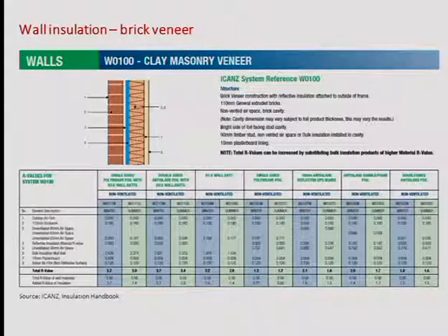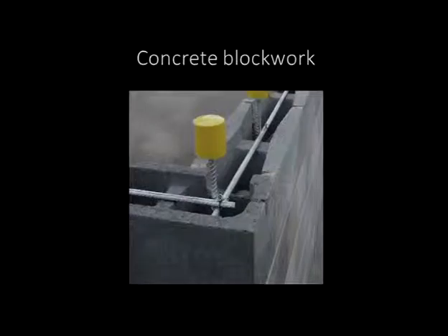All right? So even if there is the same material and type of things, no, that depends also on the thickness and disposition of layers. So the way they are sorted. So the R value you get here can be applied only to this specific section, only with those specific thicknesses and depth of the elements. All right? Generally, the bigger the better. All right? So you understand numerically, quantitatively, how the wall performs thermally. So how it's able to conduct heat.